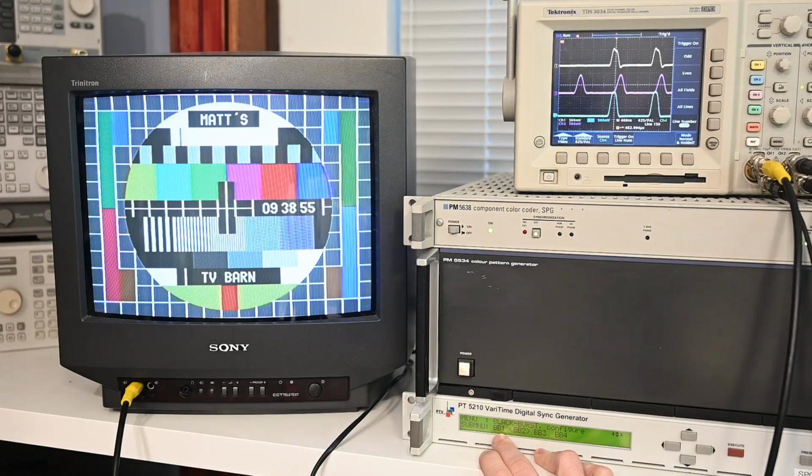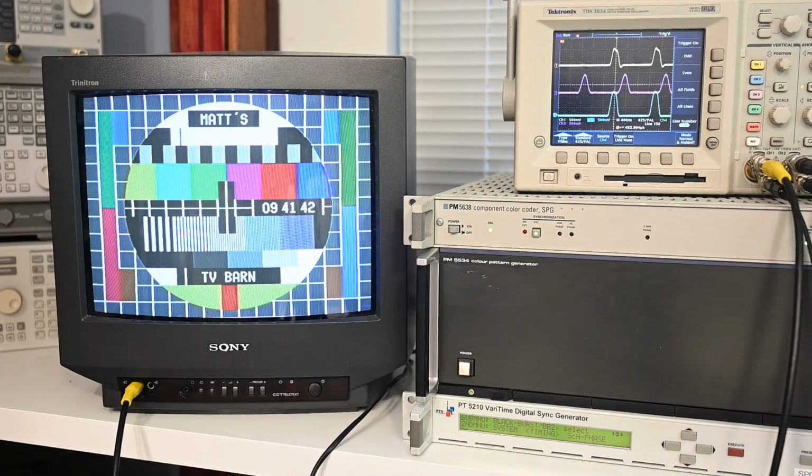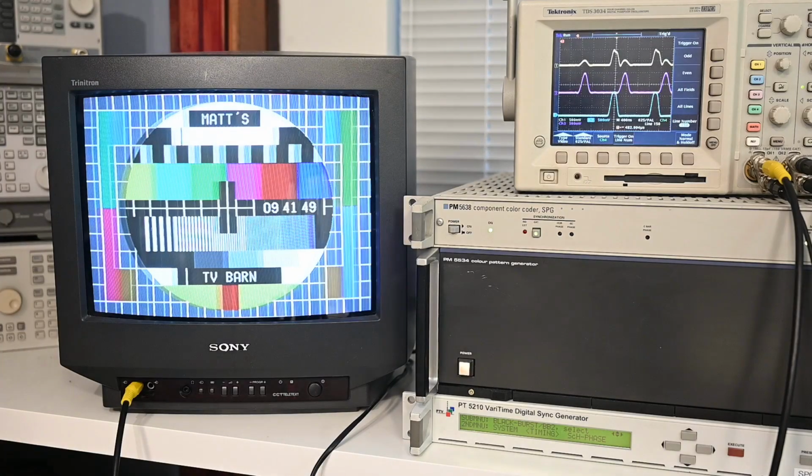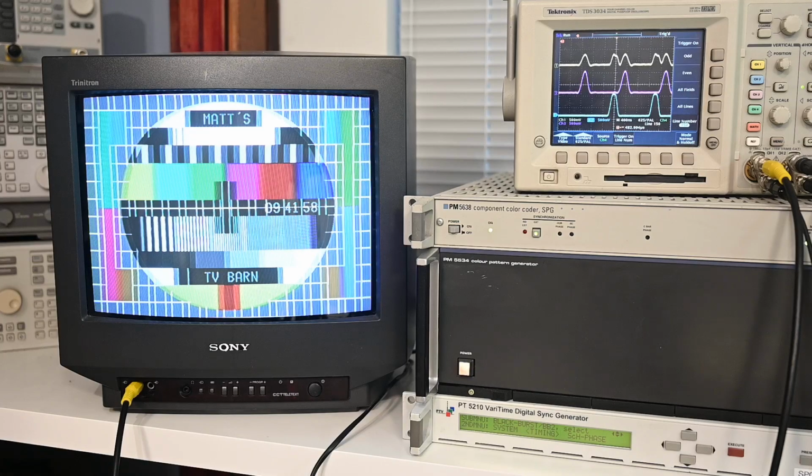This is a good signal that we're going to align to, and certainly not play around with at all. So what we're going to do on our master SPG here is go into the menu for black burst 2, and this is where we will start to play around with the timing. So first things first, let's just adjust the fader on our video mixer so that we can start to fade in the output from the AJA Kona, which as you can see is a Philips pattern.